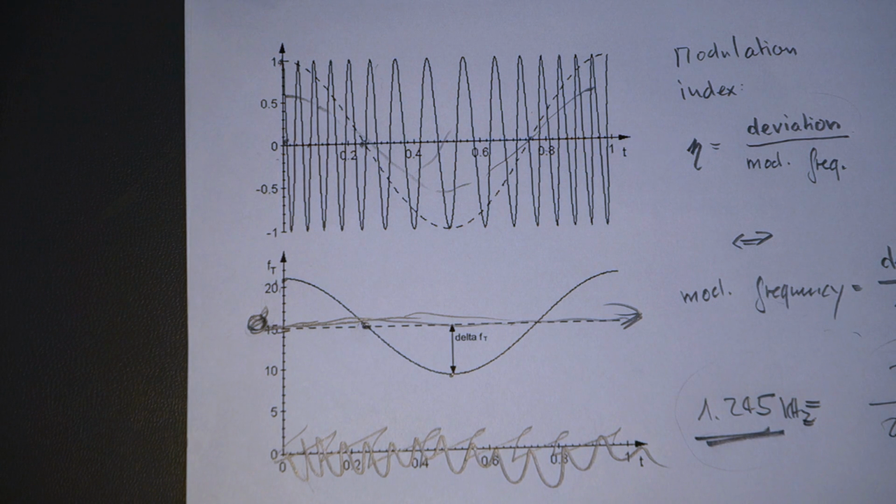And you always have to restrict the width of your signal, because if you keep going, you get more and more sidebands, and at some point you start interfering with stations that are on nearby frequencies, and of course you don't want to do that. So this is why we have to agree on a particular deviation, which might be 3 kilohertz or 5 kilohertz or whatever, but that would be an application for this.